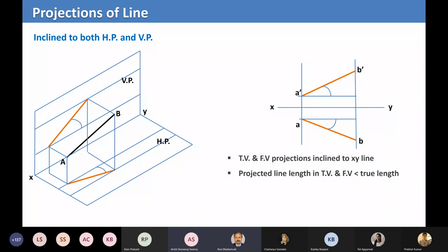Yeah, okay. Thank you for it. We may also say 30 millimeters above the horizontal plane, or 50 millimeters behind the vertical plane. So we always tell you that, so we can make out which quadrant it lies in. In mathematical terms, is it minus or plus XY coordinates? Because the origin is lying at the intersection of the horizontal and vertical planes, right?